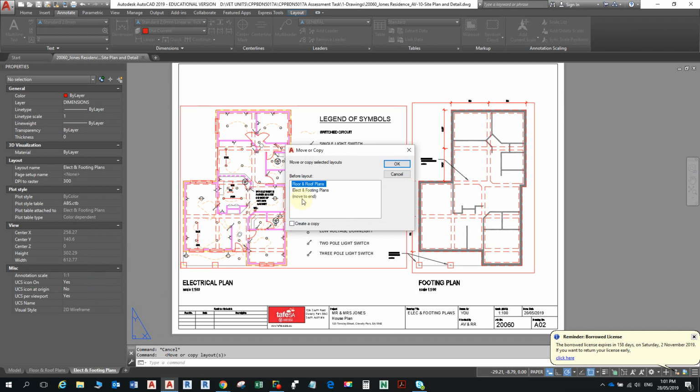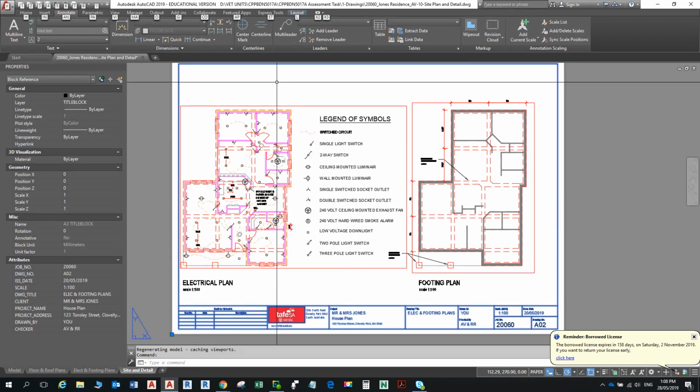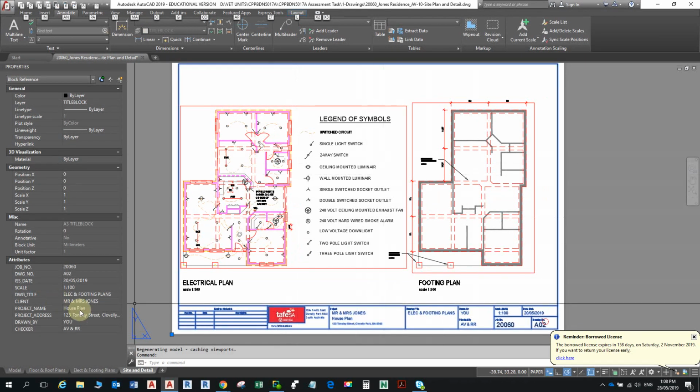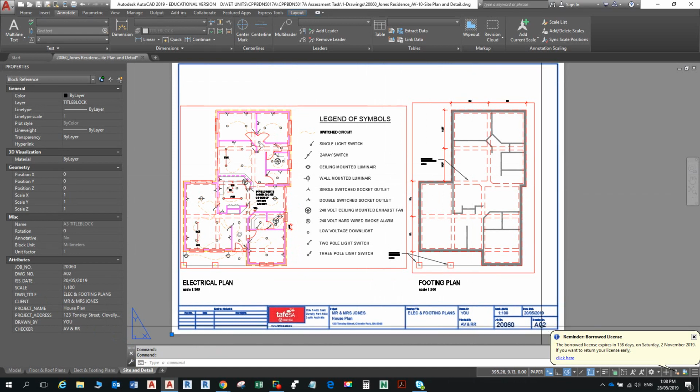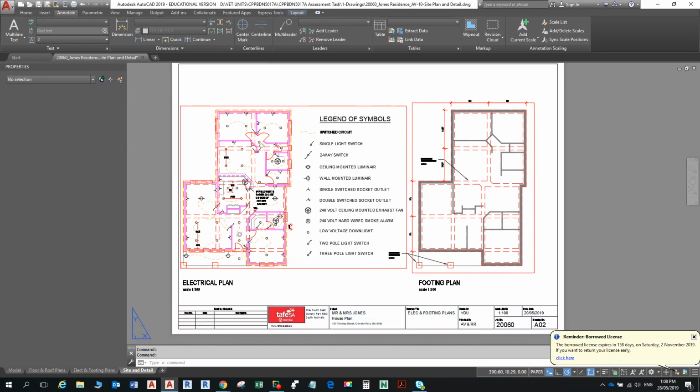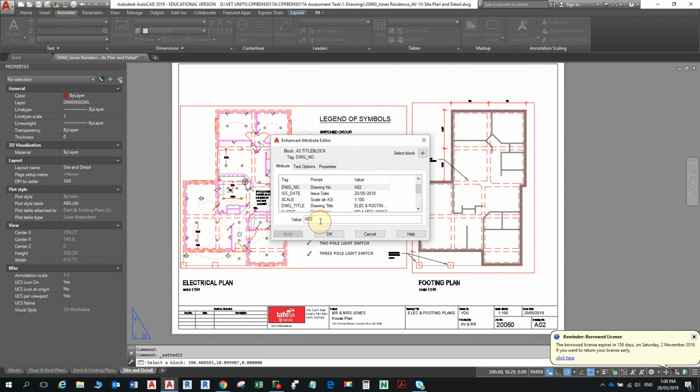And then you click on the move to end. And then you must click on the create copy bit of it and then press OK and it'll create another one and we'll rename that. All right, so for now, just open it up, have a look at that detail, rename it. And of course, just so you don't get confused, first thing you need to do is just change the name to AO3 here, or the sheet name.